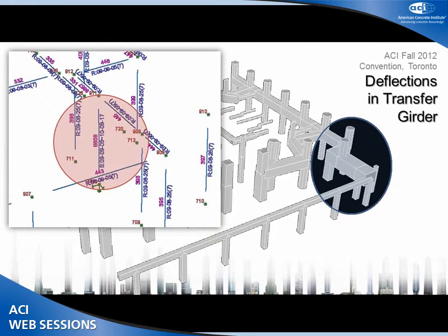Construction stage analysis was used to identify the need of temporary supports for a transfer girder, shown inside the circle. In the developed program, not only the birth date of elements, but also expiration date can be designated as a critical construction sequence. The temporary supports were modeled to be removed after 13 months, as required in the particular specification.